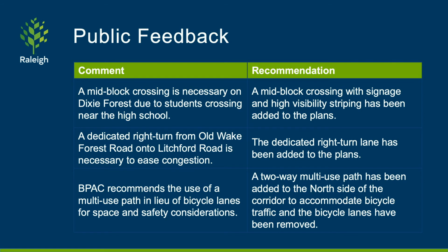One of the previous concerns was the lack of mid-block crossing on Dixie Forest to accommodate students coming and going from Millbrook High School. The crossing has been added to the design with signage and high visibility striping. Users of the corridor commented on the lack of dedicated right turn lane from Old Wake Forest Road onto Litchford Road. The design team reviewed the request and has implemented the design right turn lane to ease the logjam at the intersection during peak hours.